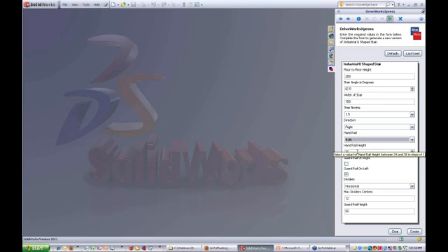Handrail height, another numeric text box. Yep, we'll leave it at 37, that's okay. Two check boxes if you want guardrails, simple tick or untick, we'll have them both. And do we want dividers on the stairs? If so, are they horizontal or vertical? We'll leave it horizontal for now. Maximum centers between them, we'll make it 20, and a guardrail height of 100.